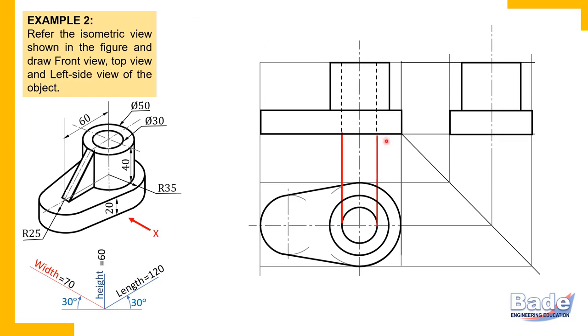Now, very important thing. In the top view it is a circle, so this hole is a rectangle in the front view. Like a cylinder, it is a cylindrical hole; in the top view any cylinder is a circle, and in the remaining two views a rectangle. So here also this hole in the top view is a circle, and here it is a rectangle. If I ask you where this hole is in the front view, don't just show me these two dotted lines. Show me this entire rectangle. Remember, like a cylinder, this is a cylindrical hole in the front view.